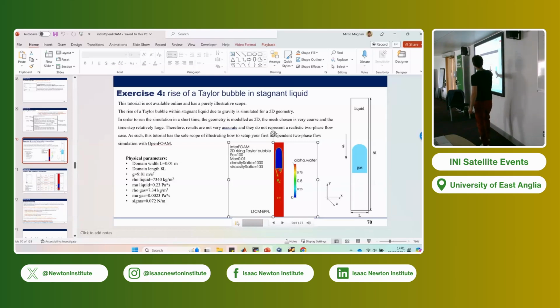And to do this tutorial, I'm explaining here in exercise 4 at the beginning how to start, where to get the files, what to modify, and then your task will be to modify it yourself. The tricky aspects are to create the geometry, to set the fluid properties. Then the case runs in 5 to 10 minutes, usually in one core. This is only 3,000 cells, I believe.